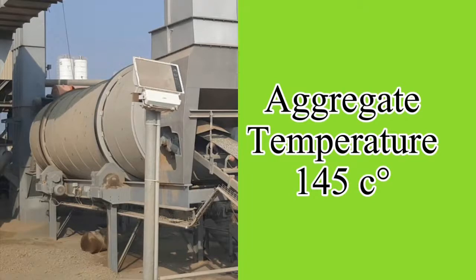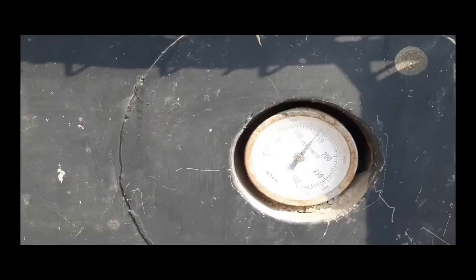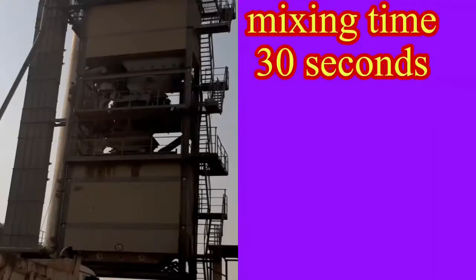Here note the temperature of all aggregates. Aggregate temperature should be 145 centigrade. Then you check the temperature of bitumen. You can check the bitumen temperature from the gauge with bitumen tank, or you can check directly from the operating system. Then you select the mixing timing. Select mixing timing as 30 seconds.